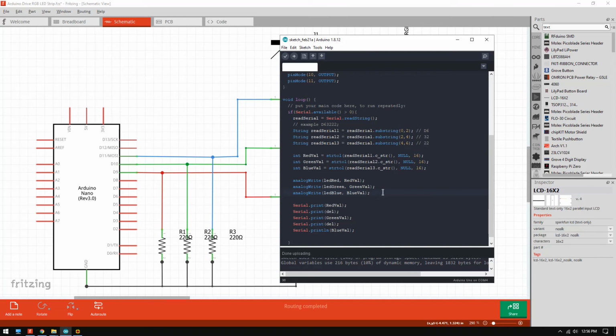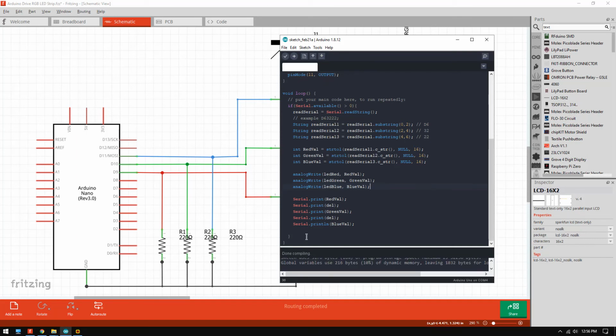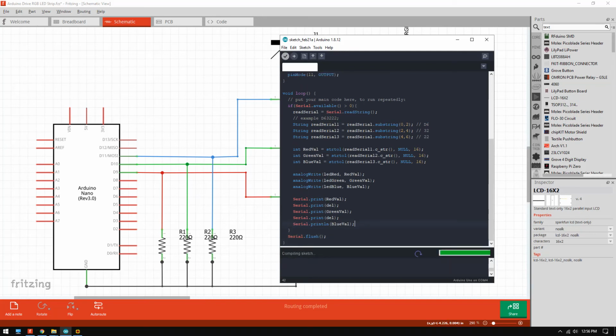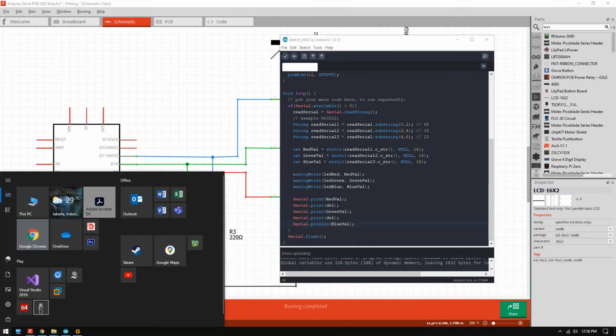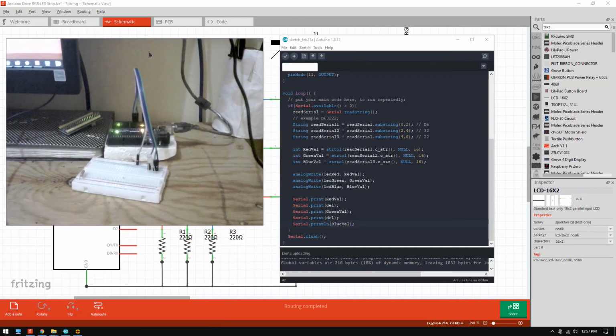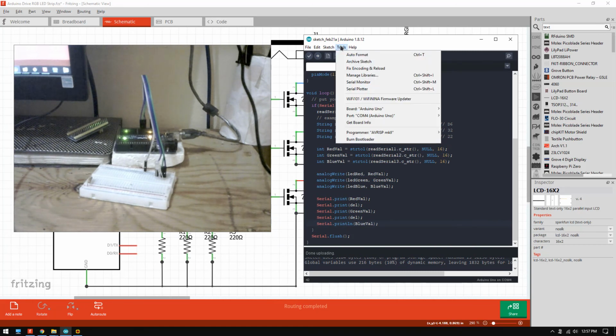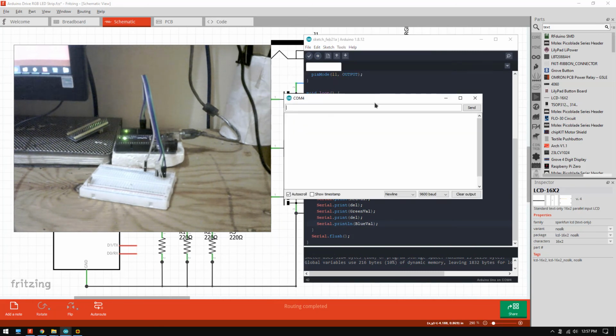Okay. Now I don't know if we require a flush, maybe Serial.flush. So we remove all the values inside the serial. Upload. Okay, now I'm gonna show you what is the effect of our configuration. So here, get set up, and then go to the serial monitor.